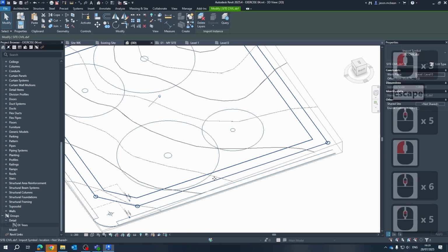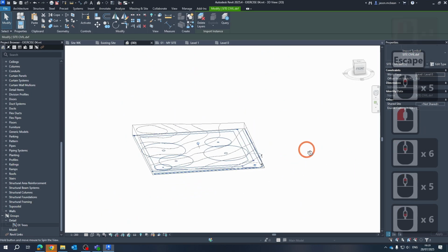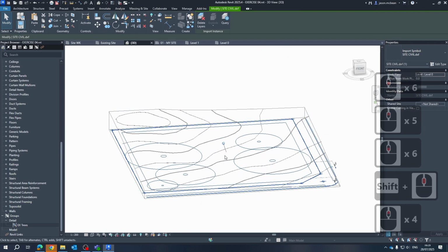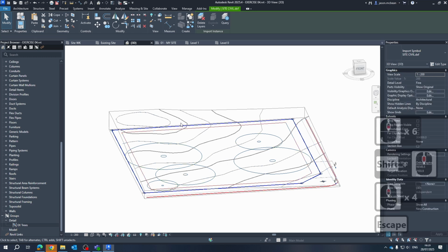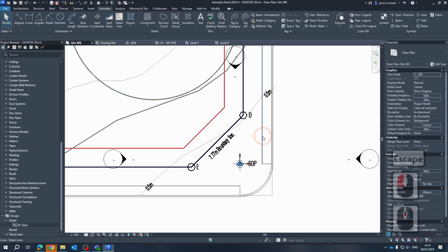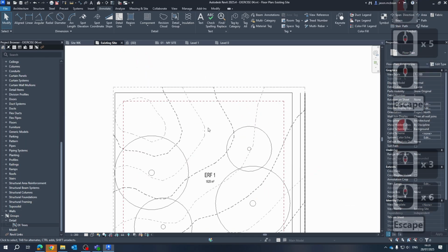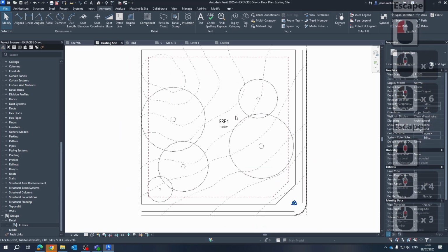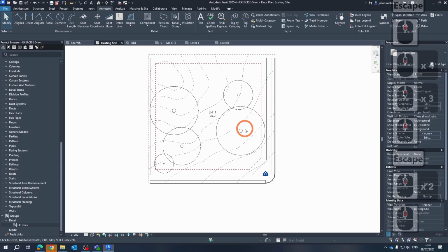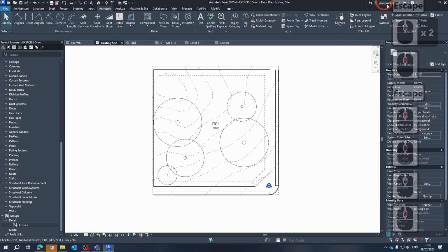Now, if this was a 3D line work in that view, everything that was below the topography will never display. So hence we've got to use annotation lines and drafting elements to put over your view. That's very important.